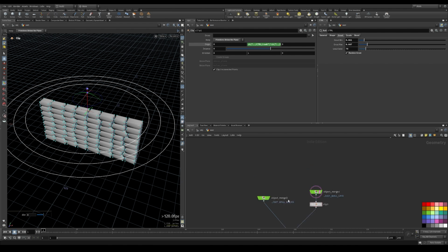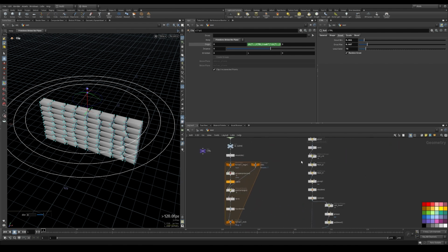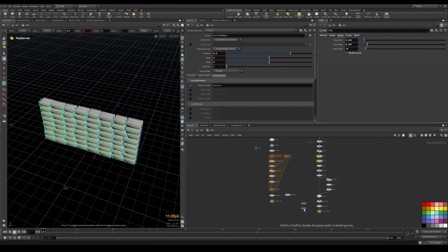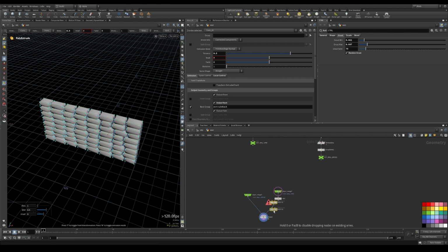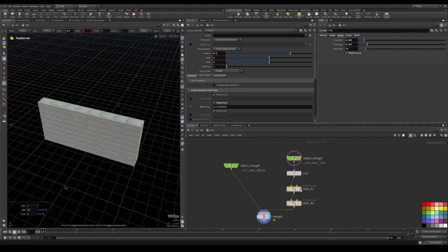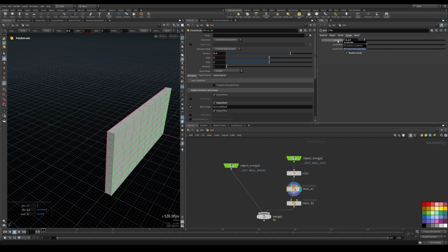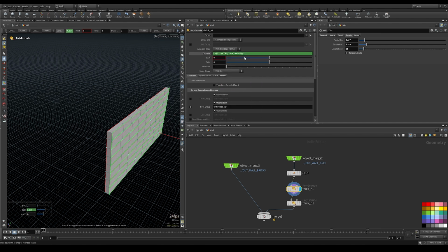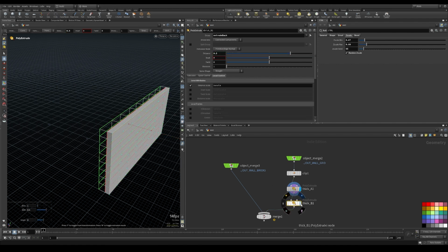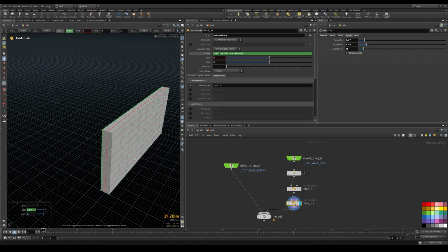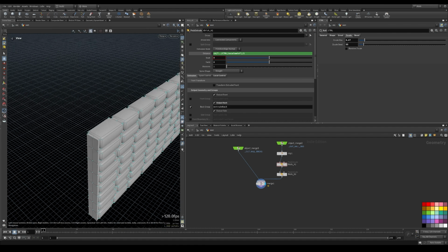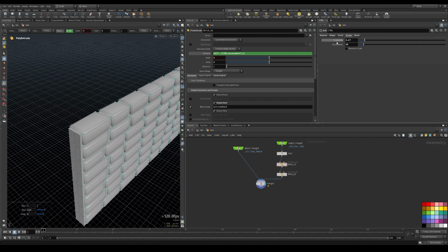And now for the thickness, we can copy the 2 extrusion we did up here, and let's drag it over here. Display the first one. And for the thickness, this time we want to use the scale minimum, the Z scale minimum, so copy parameter. We want to paste it here and divide it by 2 because we are doing 2 extrusions, so copy the same value on the second one. And they should match. Oh, this is the Z scale max.